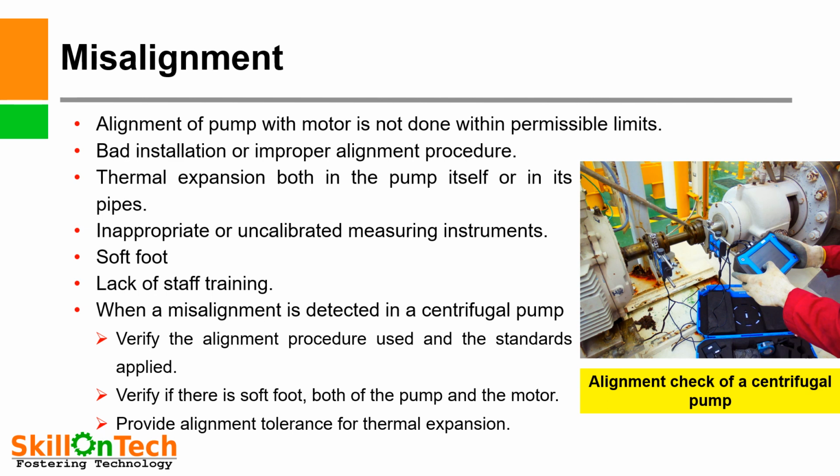Verify if there is a soft foot on both the pump and motor, then the soft foot shall be removed. Provide alignment tolerance for thermal expansion. During the operation of the pump, they come under temperature, so thermal expansion shall be considered while carrying out the alignment, and tolerances are to be provided for thermal expansion.